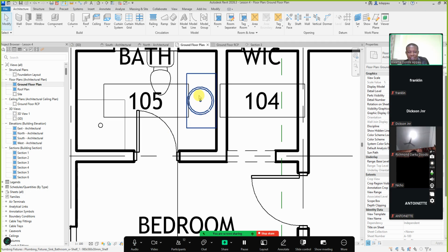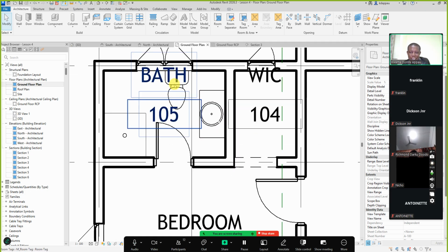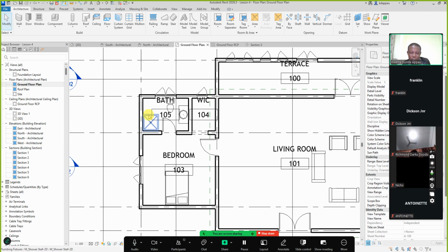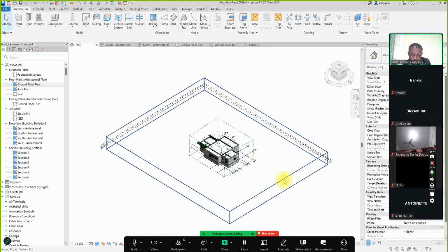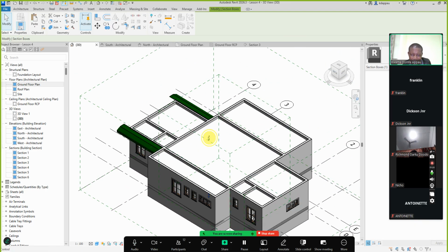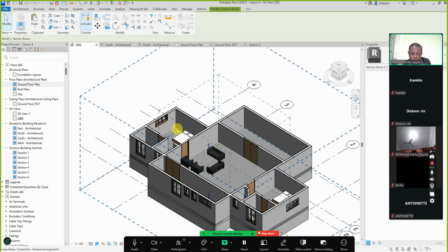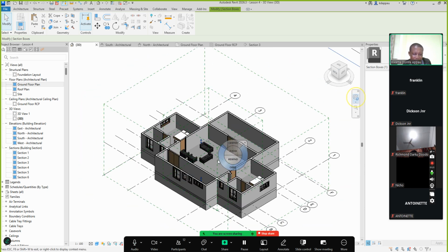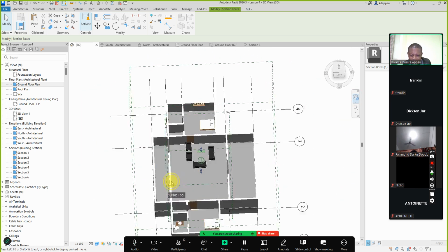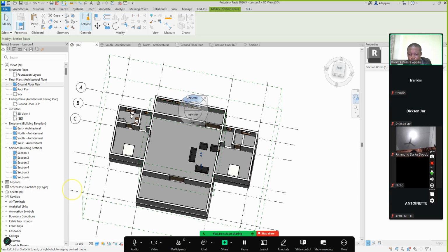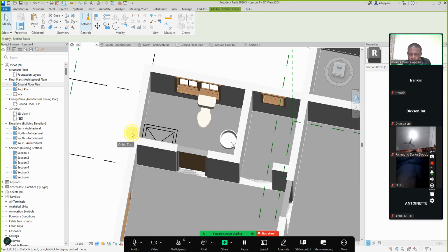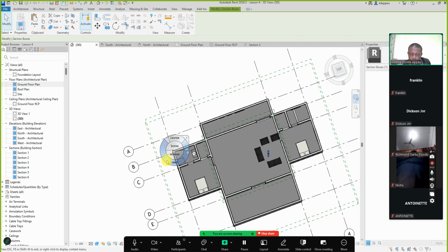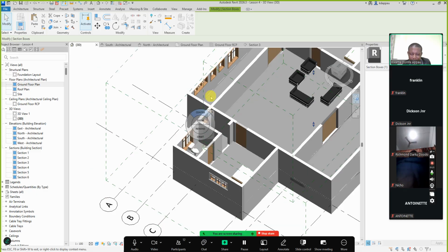So when I open it, I can access my sink, I can access my WC, then I can have my wash tab here. If I go to a 3D view and I take my section box and bring it down a bit this way, and I take my orbit and orbit it a bit, I can see my bathroom here, which I just worked on.